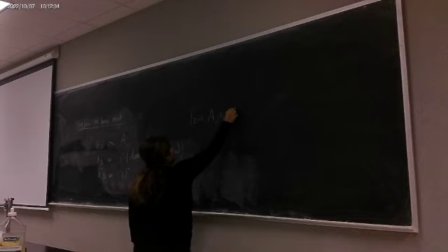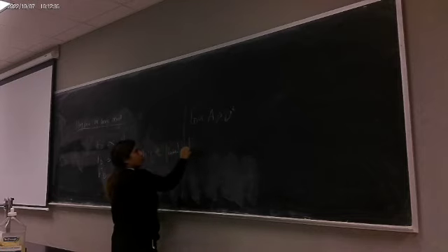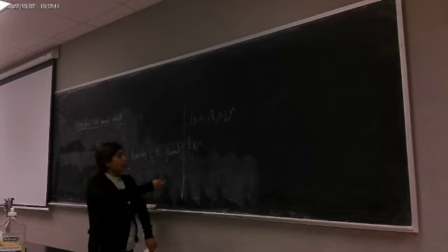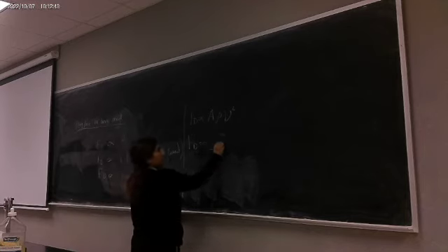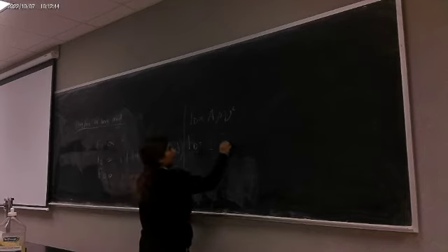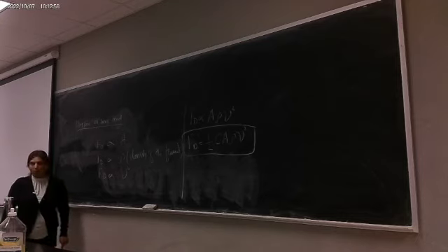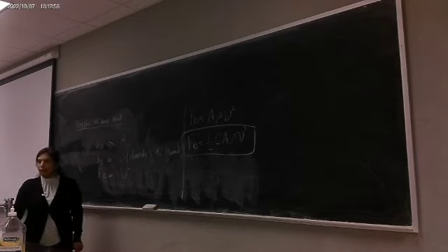If we put them together, it is proportional to A rho V squared. The proportionality sign goes away when you bring in the constant, half C A rho V squared. That's the formula for drag force on big objects moving through fluids. Big objects with some surface area, macroscopic objects that you can see with the naked eye.